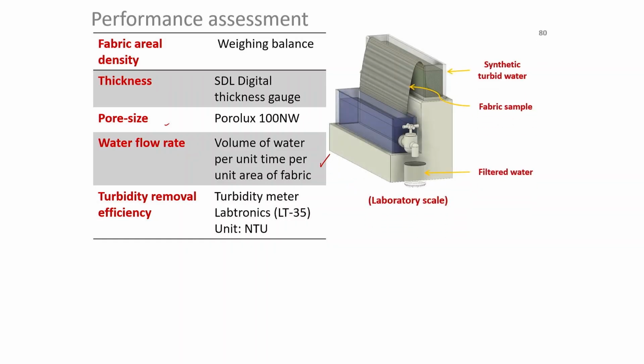This is the system here. Now, here it is the contaminated water; this is the base. Here we have used synthetic turbid water. So, standard particles we have used, not the normal soil, to make the system reproducible and reportable. So, we have used the standard turbid water, and this is the fabric specimen, and after the first stage filtration we get the filtered water.